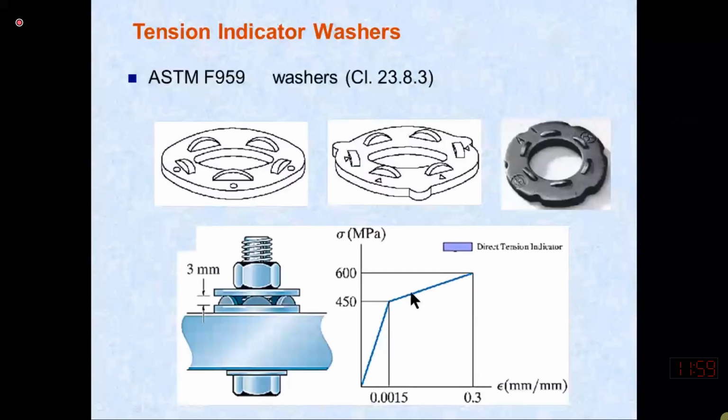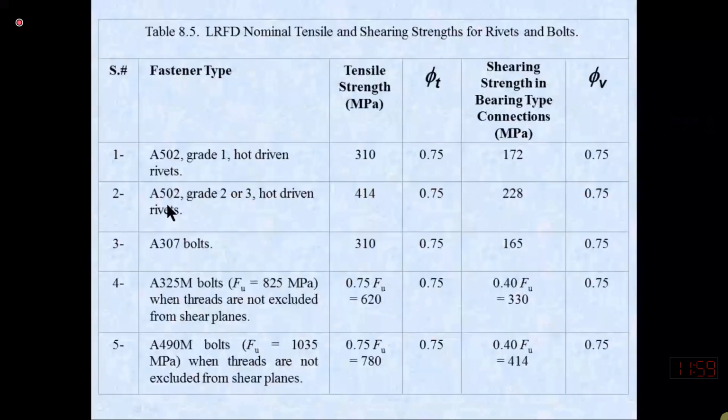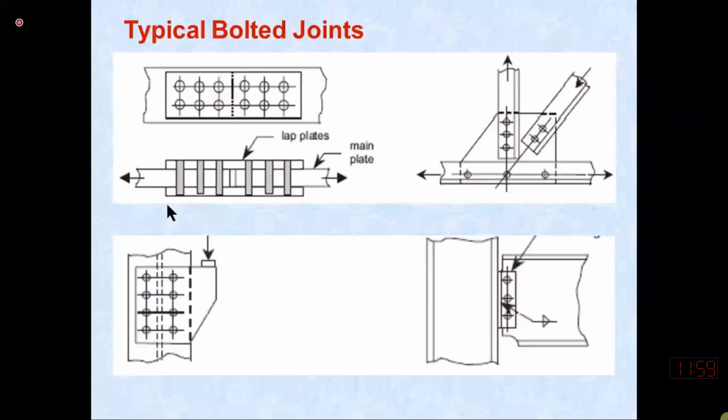In case of the bracket, we are connecting the gusset plate with the fasteners to the flanges, and they are provided in 2 rows. In case of the simple shear connection, we are using an angle section to connect the web of the girder with the flange of the column.